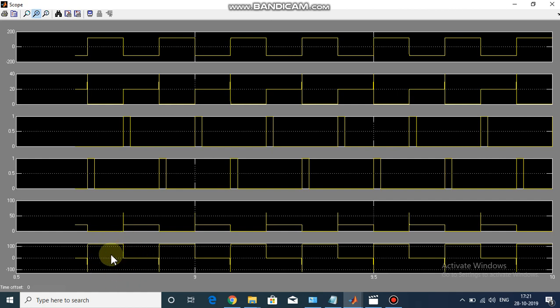And the last one is the SCR voltage, which goes negative. The negative spike indicates that there is a negative voltage appearing across the SCR. Now the common question that you are going to be asked by the professor is why can't we see the SCR being turned off? Like, why are these sharp?